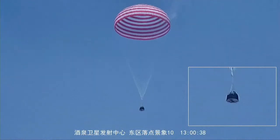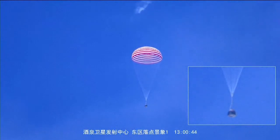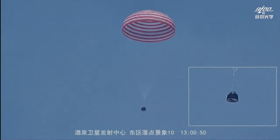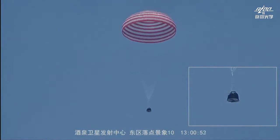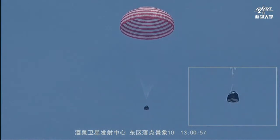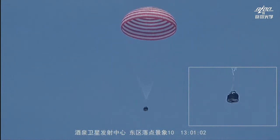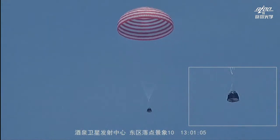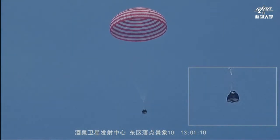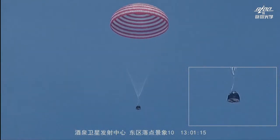As Professor Zhang mentioned, we can control the attitude of the capsule during the re-entry. This is the function of the propulsion system on board the re-entry capsule, but it only changes the direction in the roll direction, to change the direction of the lift. With the change of the lift, we can change the trajectory to the landing point. So it's not falling through the atmosphere; it's flying through it. Flying, yes. And the engine is basically like the aircraft wings flipping up and down. Right, it's doing that function.